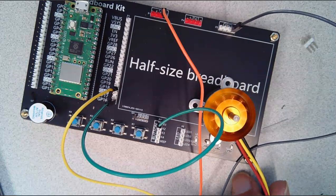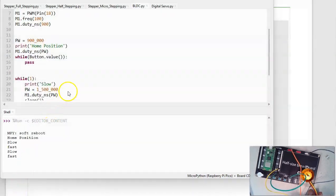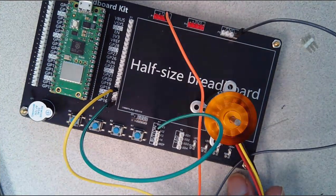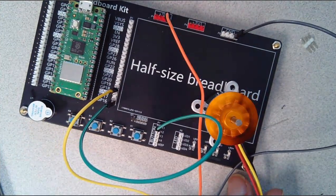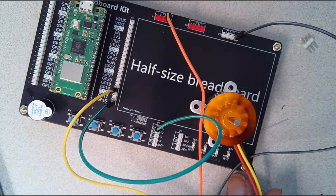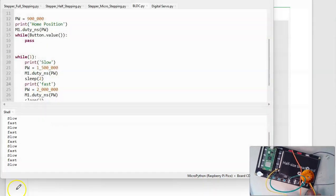It now varies the pulse width between 1.5 and 2 milliseconds. And you can hear the speed changing. So that is a brushless DC motor. Vary the pulse width, I can make it go faster, slower, stuff like that.